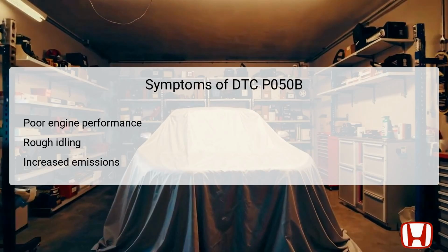Increased emissions might be observed, leading to a potential failure in emissions tests, as the improper ignition timing can cause incomplete combustion. These symptoms may also contribute to additional diagnostic trouble codes if the underlying issues are not resolved promptly. Therefore, it's essential to monitor these symptoms closely, as they can also indicate other underlying problems within the engine's ignition and air intake systems.